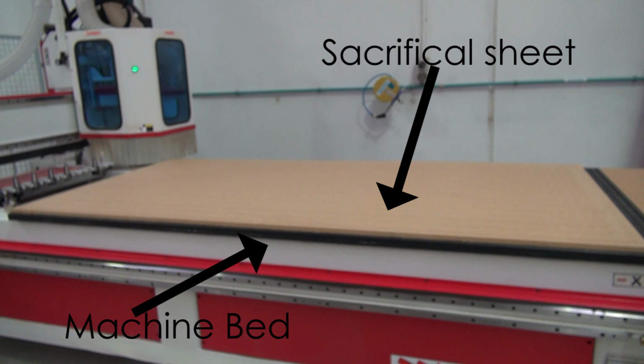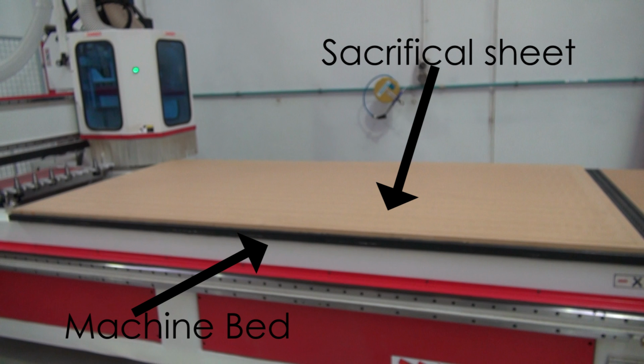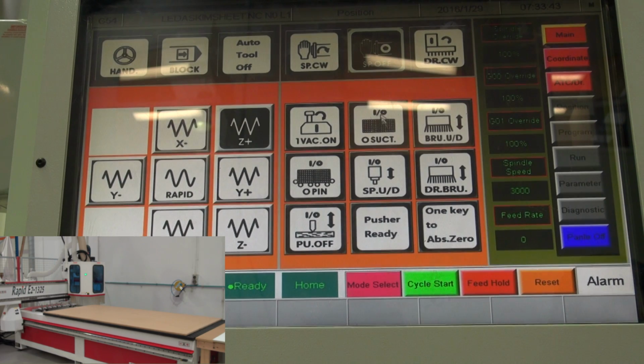For this reason, the operator will be required to skim the sheet. When skimming is performed, the cutting removes all of the grooves from the surface of the sacrificial sheet, ensuring the material can be placed on the sheet without any vacuum loss. To skim a sheet on the CNC, the following steps have to be taken.